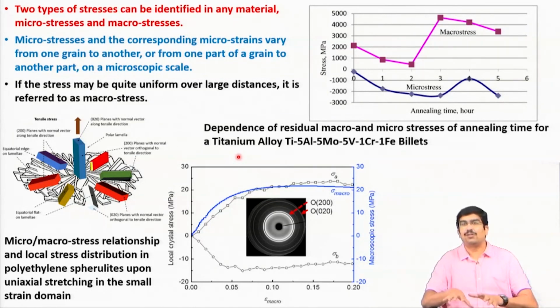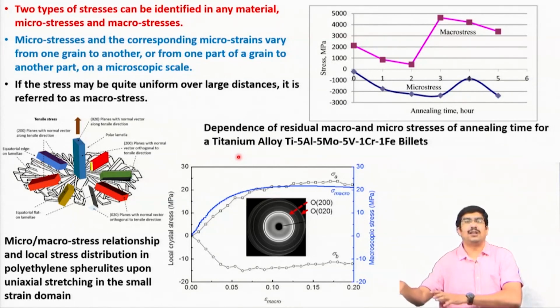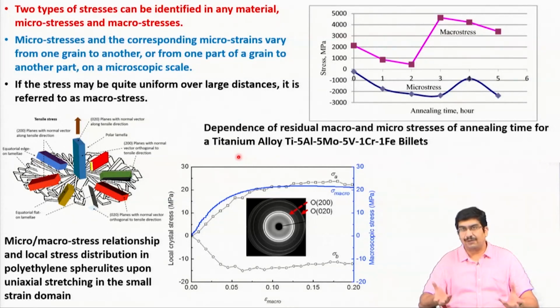That means on a submicron scale possibly, and if you think of it in that way, if you have a submicron size grain, even within the grain you have this dislocation substructure formation, and that dislocation substructure even varies from grain to grain, because many different grains may have different orientations, and dislocations of course will be completely different, the type of dislocations will evolve, dislocation density will be different, and so on and so forth. So, basically we can imagine that a strain accumulation is happening in the material at micro scale.